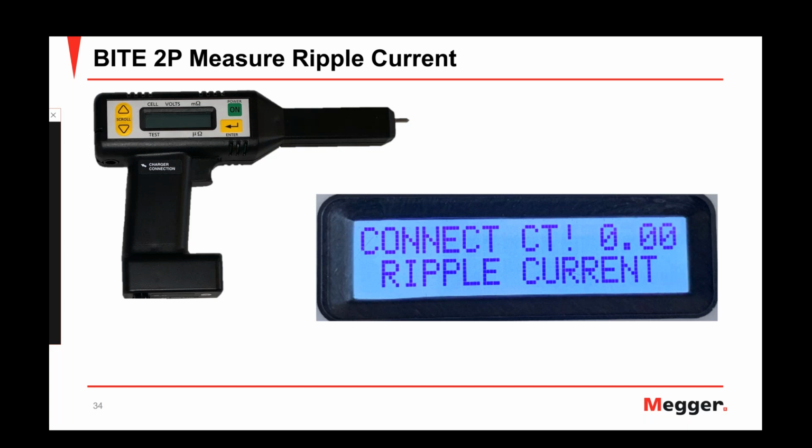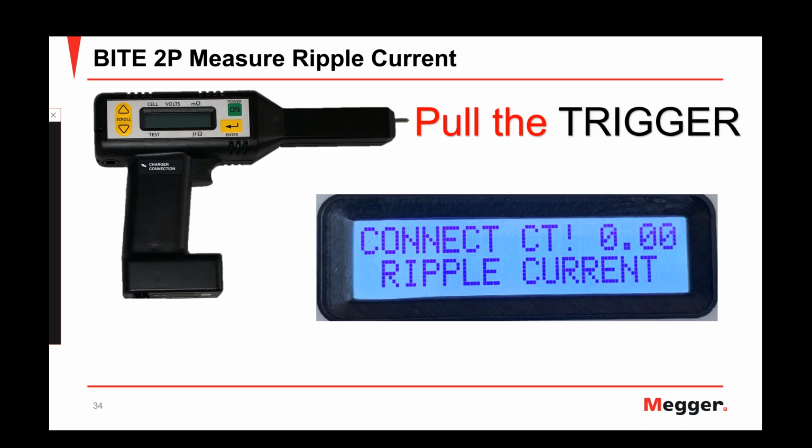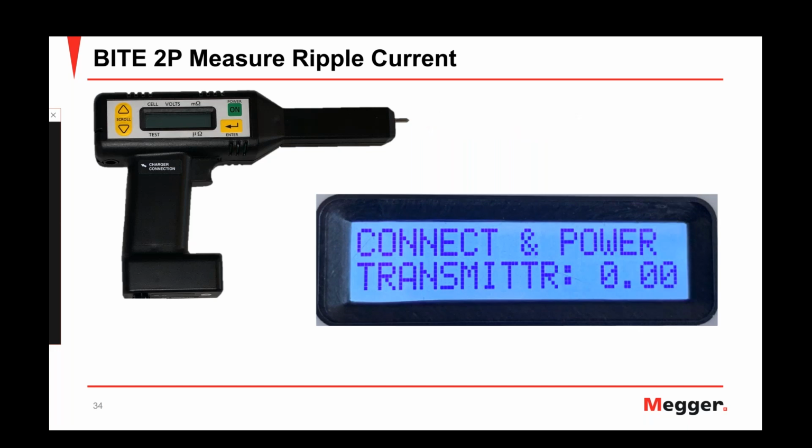Whenever we take this measurement, it's going to take the measurement using the CT that you've already applied to the battery string. So all you really need to do is refer to the screen on the receiver to see if there is any ripple current. And whenever you have a stable reading, go ahead and pull the trigger on the receiver unit to save that value. The next prompt is going to ask you to connect and power the current transmitter. We've already connected it to each end of the string. However, let's look at how to inject current.